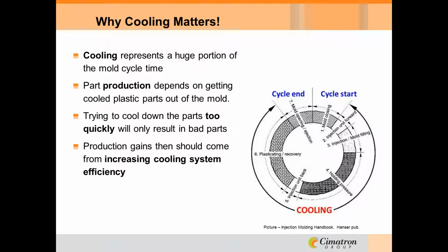But just rapidly cooling the part isn't the same as efficiently cooling it. Controlled, repetitive cooling around the entire part is also really vital to controlling the dimensional stability and the mechanical properties of the plastic part time after time. Meaning, a properly cooled part won't be as likely to warp or be stressed or brittle. The best way then to ensure a successful and profitable run of plastic parts is to make sure the mold has a well-designed cooling system.